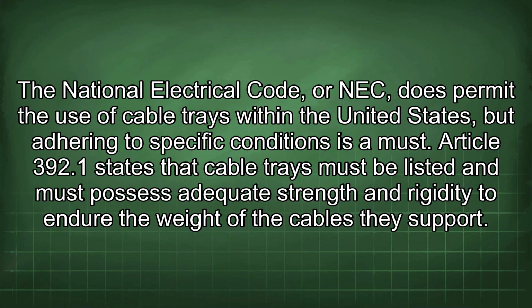The National Electrical Code, or NEC, does permit the use of cable trays within the United States, but adhering to specific conditions is a must. Article 392.1 states that cable trays must be listed and must possess adequate strength and rigidity to endure the weight of the cables they support.